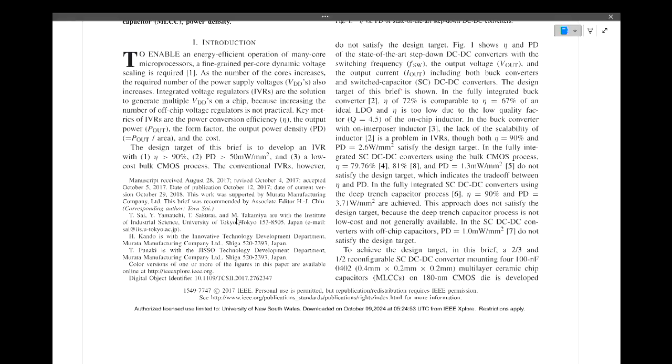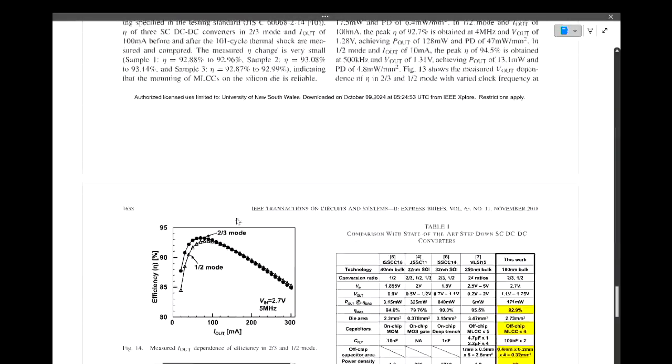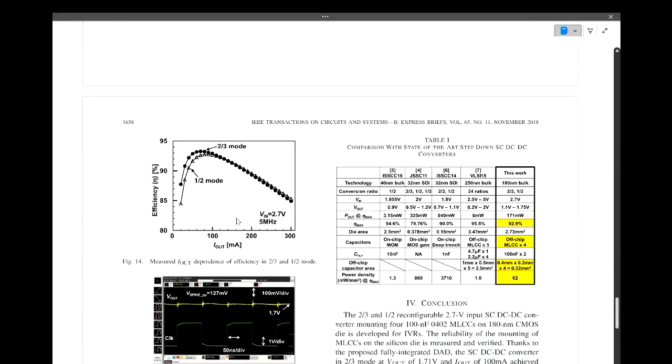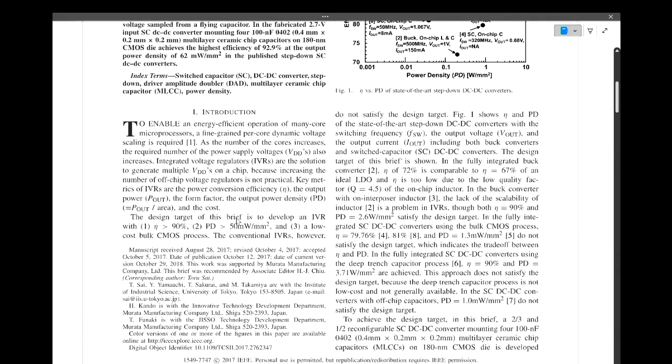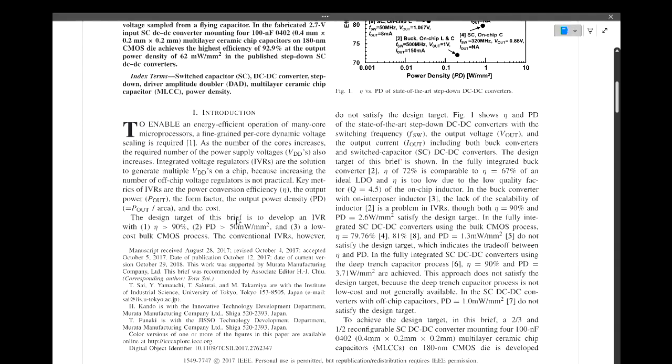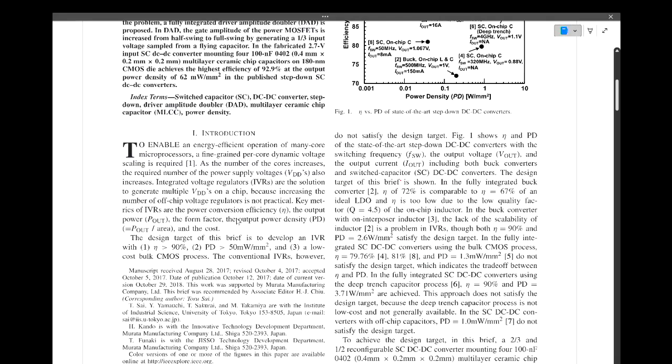Now the charge flows into that because it's connected to the virtual ground, so you have to have current flowing in. So it's connected until both these two are fully charged. So you always wait until the charge is settled, every clock period. You make the assumption that it always settles completely.